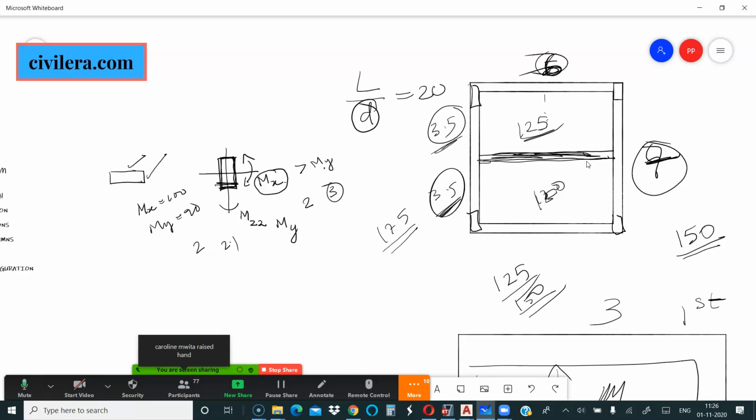So I would suggest you always get the thickness of the slab right in your scheme. If you use 200 thickness instead of 100, your entire thing can go crazy. So I would always recommend you fine tune and finalize your slab thickness first.